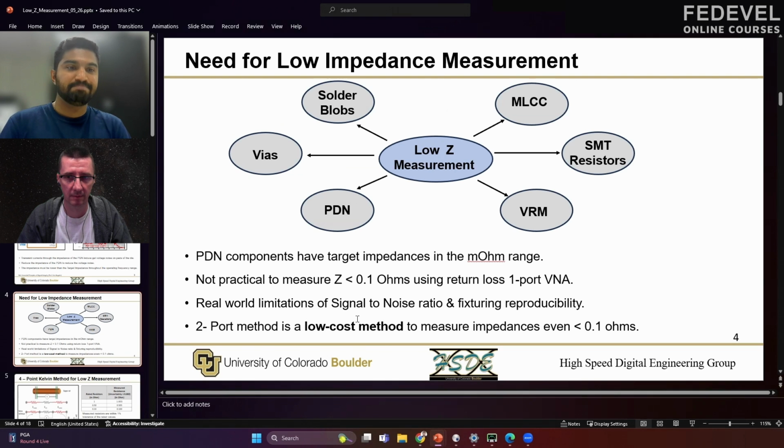Okay, and basically with this special device, we can actually measure the path between the power supply and the chip. We can measure the impedance or properties of this path. And what is special about this is that we are measuring very low impedances. That's why we need this kind of special device. Okay, and a little bit later you will explain what kind of device we are using, so anyone can buy it. Yes, definitely.